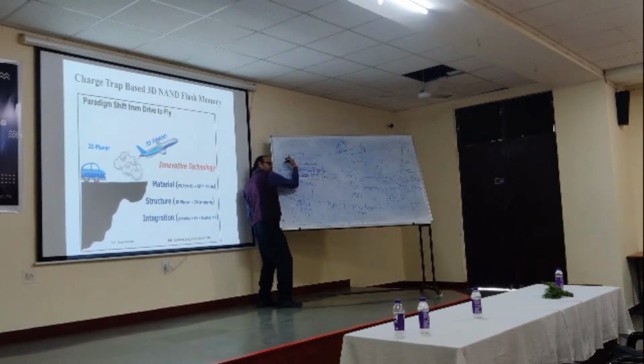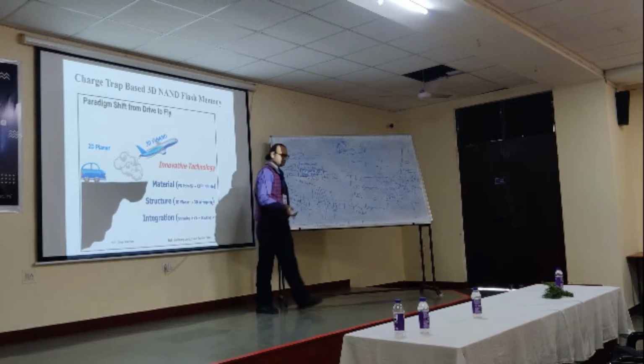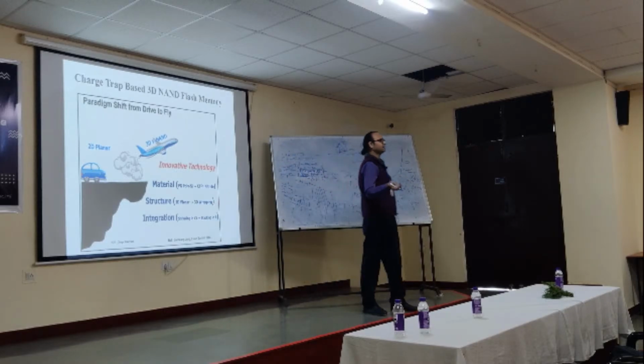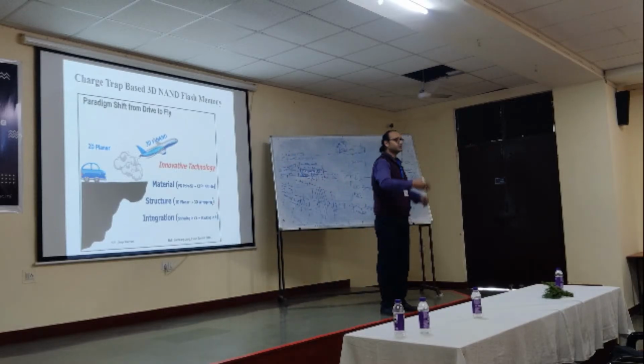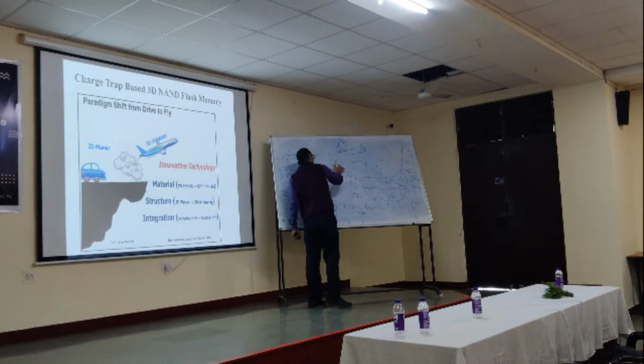Okay, just tilt it. So we will etch holes. Okay, we will deposit silicon, we will deposit oxide, we will deposit nitride layer, we will deposit oxide and then metal. And transistors will be, suppose this is one transistor, this is another transistor, and so on. So recently Micron has released its 230 or 240 layered, and we call it NAND because all the transistors are in series.